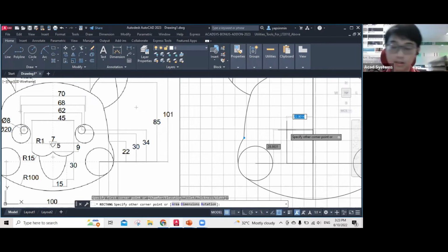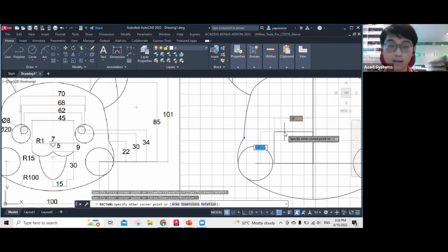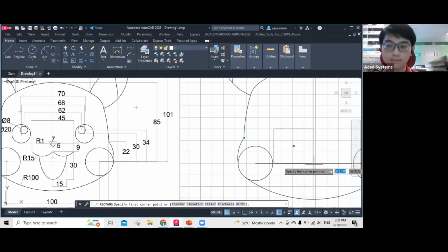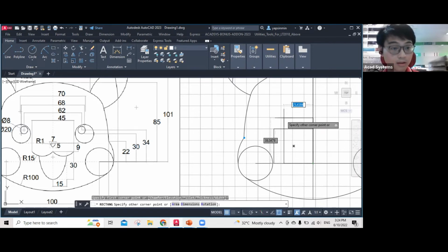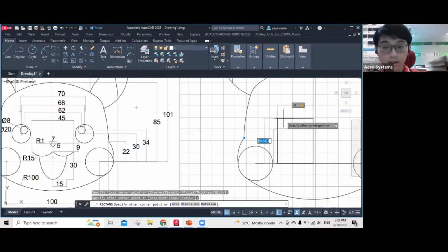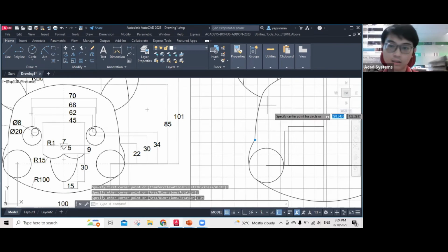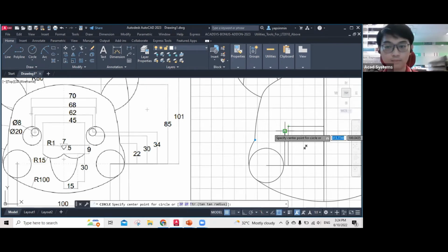And the first one is going to be 34, the bigger one, the bigger circle, 34 and 30. Enter. And move to the second circle, which is the smaller one. It's going to be 31, and the X position is, and the Y position is 34. Let's anchor this, enter, and then got it point. So these 2 points will be our center point.